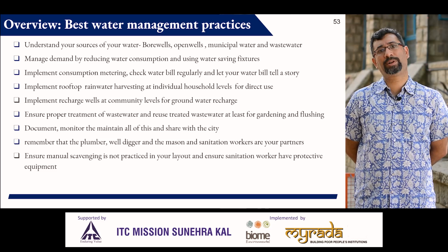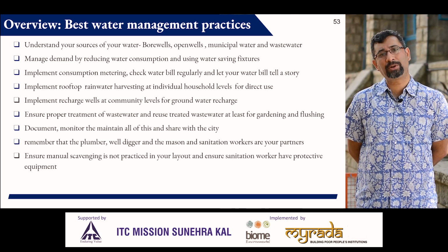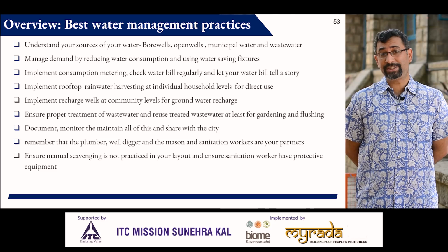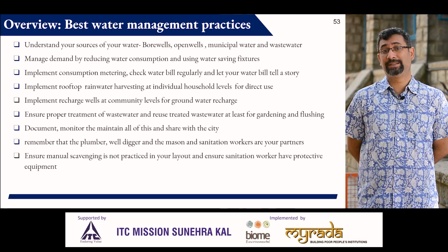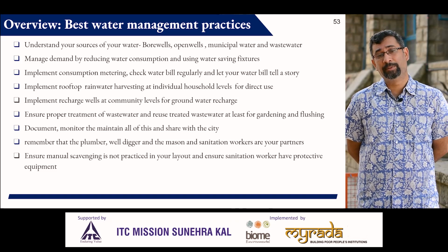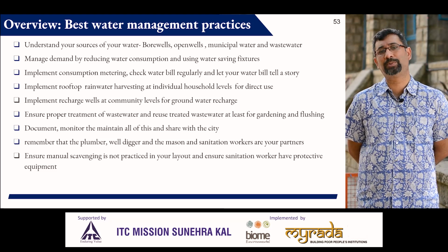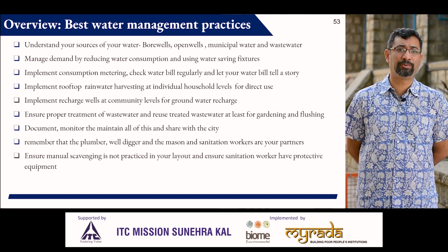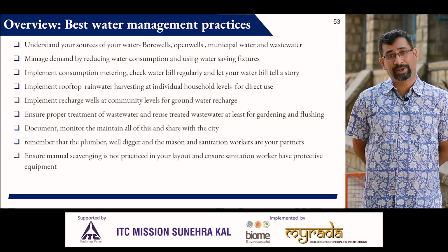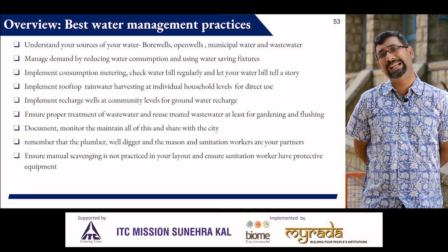So you can capture rainwater from common catchments and private catchments which you cannot store and ensure that you recharge groundwater, because we are all dependent on groundwater either through wells or through bore wells. When we are recharging water, however, remember that the quality of the water we are recharging should be clean. We should ensure that it's not getting mixed with sewage. We should ensure it's not getting mixed with solid waste. We should put our recharge wells in appropriate places, not very close to electrical cables or sewage lines.